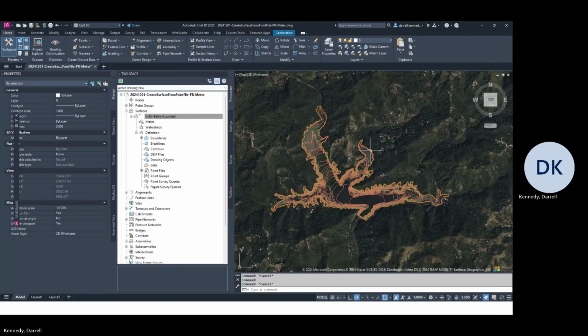All right. So I've shown you guys a few different ways. I've shown you how to import using an XYZ. I've shown you how to import using a CSV. I've processed the CSV file so that it's able to be imported. I've done a few different ways of modifying the surface properties when you have points that cause an irregular surface or a large triangle length. You can set it in the surface properties. You can add a boundary line. I've shown you how to set the coordinate system. We've done a few different miscellaneous items pertaining to changing the surface styles.